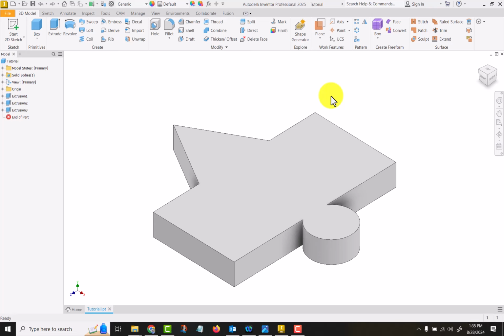All right, this week I want to talk about work planes, the axes, work axes, and points, work points. We use these things to give us a sketching plane or a sketching look direction for some rather complex and complicated parts. And the most common is going to be the work plane.